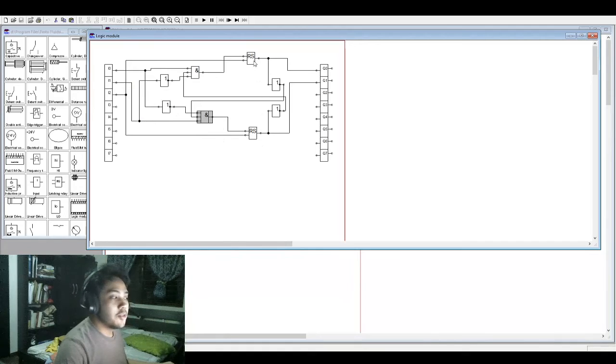Now, since the latching relay block has two ports, the second port is dedicated to the third input, which is PB3, since based on the condition we need to satisfy stated in the problem, PB3 is the switch that will reset the whole system.